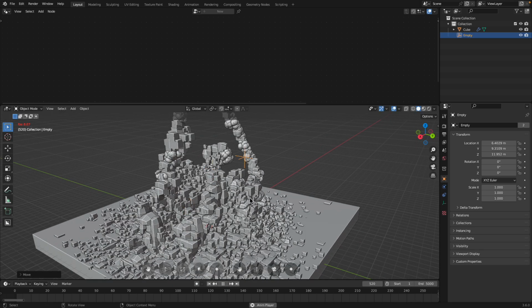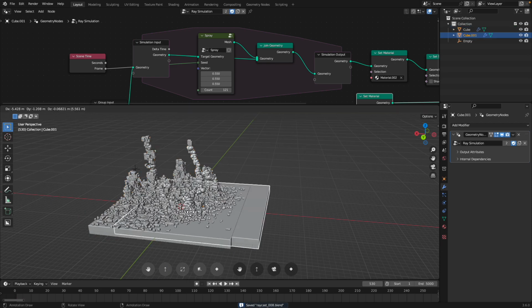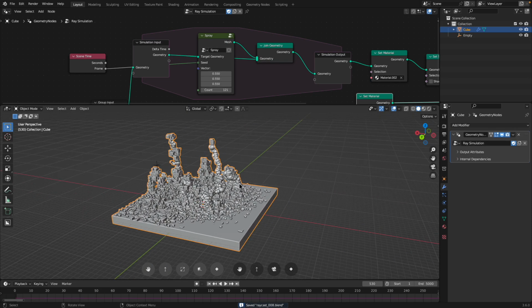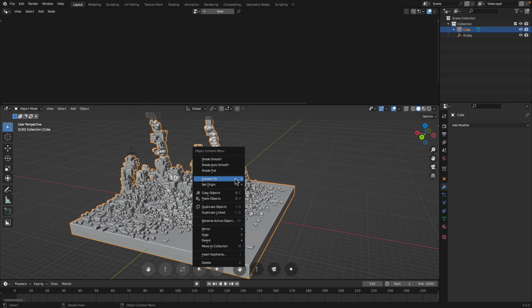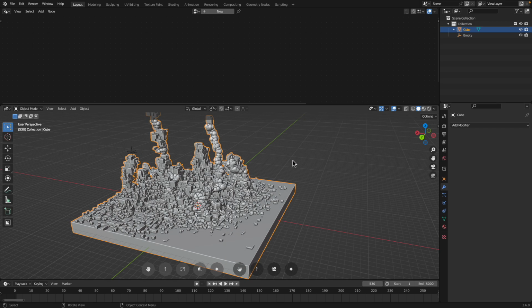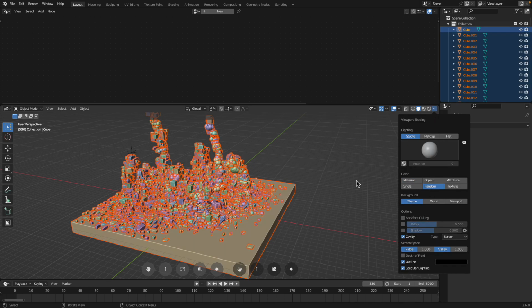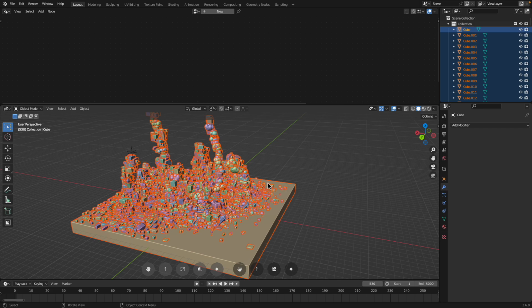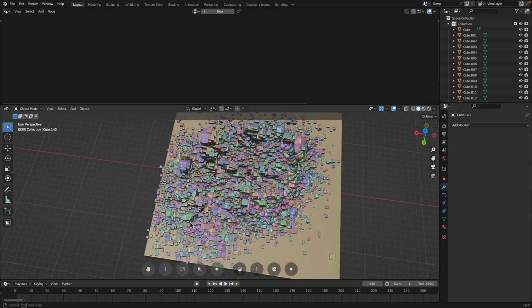At the moment, I think it's really building up multiple surface objects. Maybe there's a way to just combine everything. What I mean is, if I finish with this and then right click and convert to mesh, and then F3 separate by loose part, I believe they are all made of different random objects. Okay, so that's probably why it's getting slower and slower, because we have lots of objects being generated every single time.